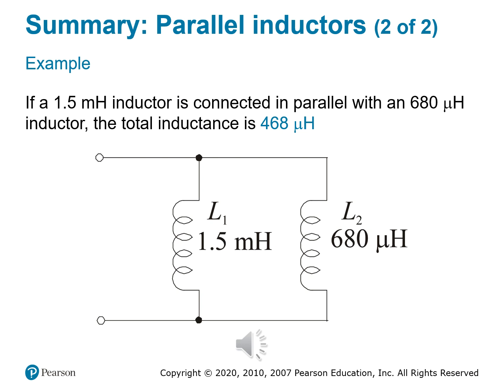And why might you wire inductors this way? This is kind of an important question for design. Again, to reduce total inductance without buying a single smaller inductor, to share current across components and improve thermal performance, or maybe to fine tune circuit's response time or filter bandwidth or resonant frequency. Again, another thing to keep in mind here is for accurate results, the inductors should be physically separated or shielded to avoid mutual inductance skewing that outcome.